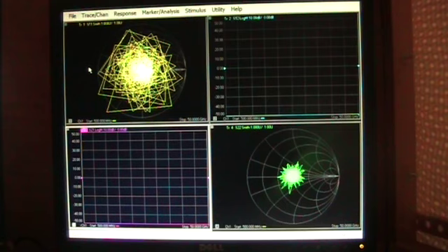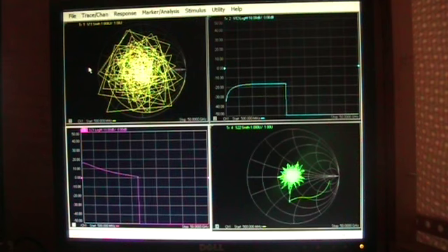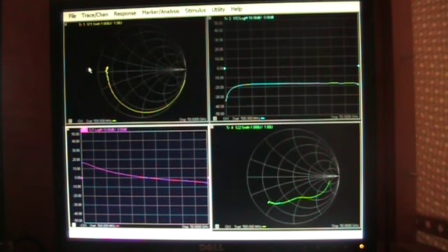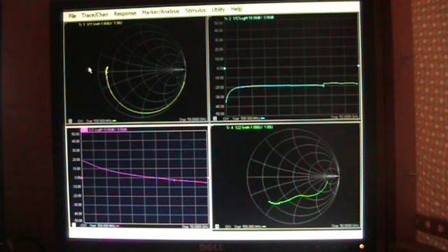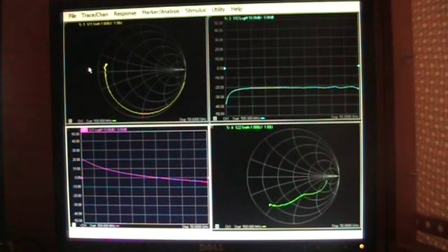Once the bias points are found, we'll step through, and in this particular state file you'll see S2P files being captured. These S2Ps will eventually be a part of the extracted noise parameter results. These aren't used as a part of the noise figure measurement. They're merely sent out as part of the noise parameters in the Touchstone format. So I believe there are 4 bias conditions being run in this particular DUT.